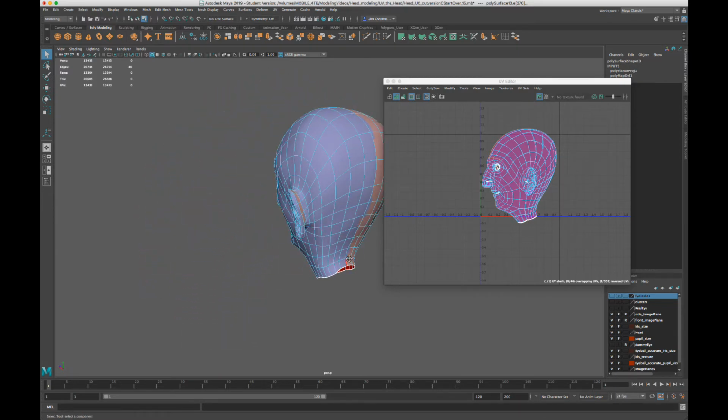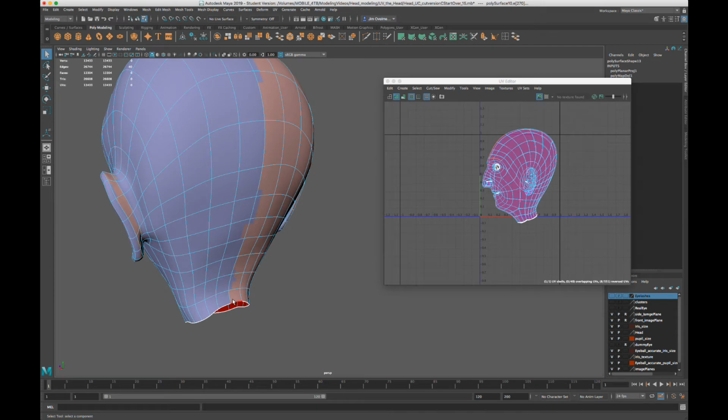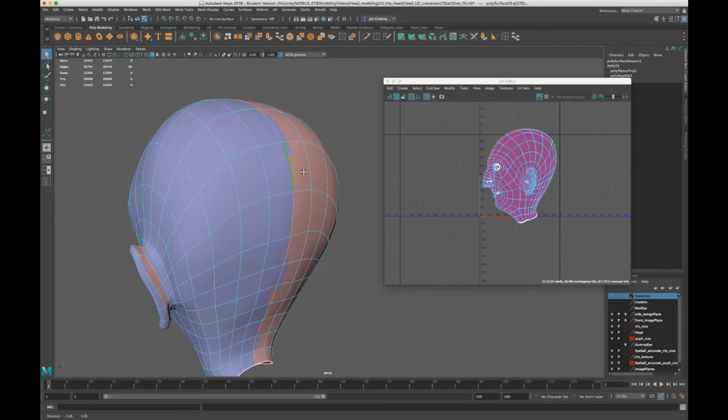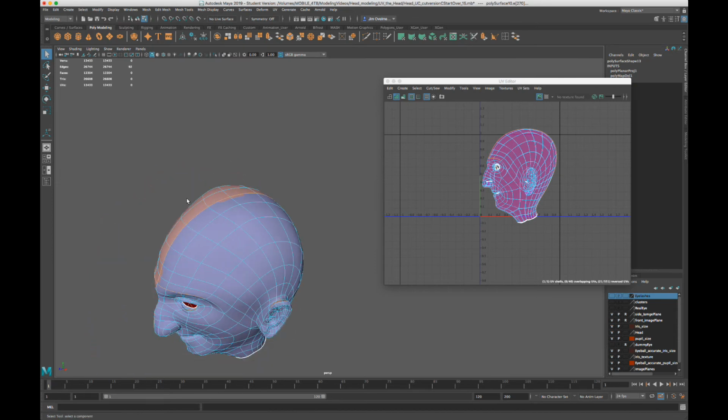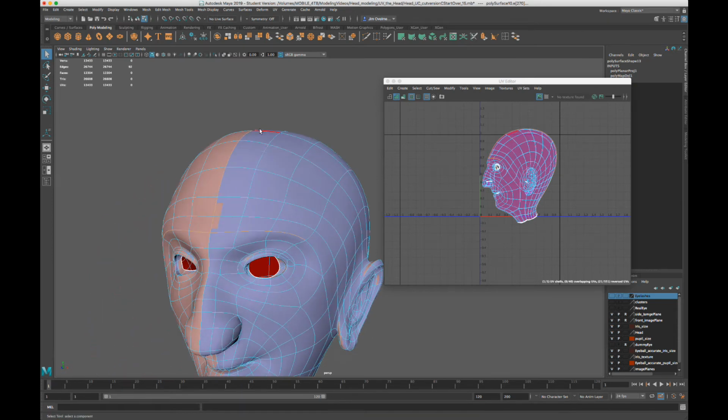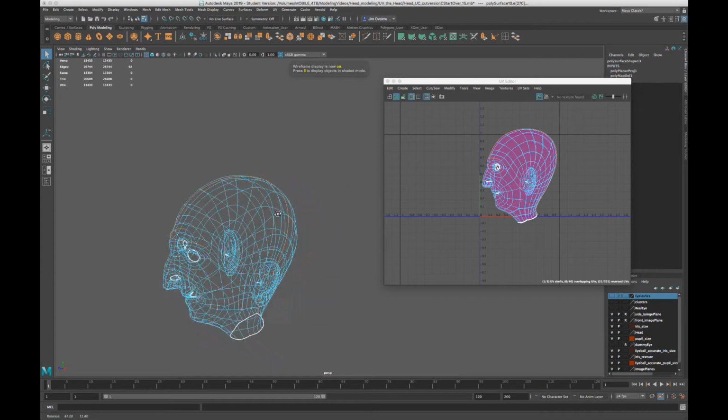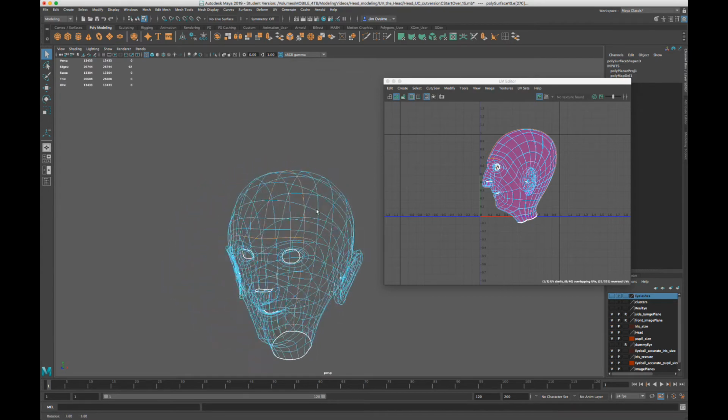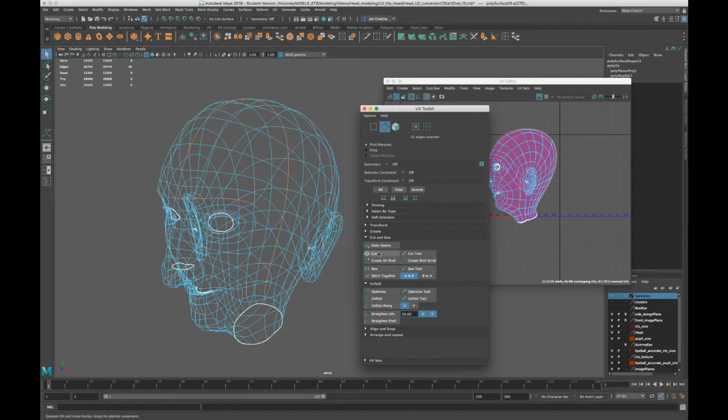If you hold shift down, that is, and double click, you see how that whole line, edge all the way between, becomes selected, that range. So let's double check. Let's look in the view and make sure we don't have any other edges we don't want selected. Here's the toolkit, UV toolkit, and we have our cut tool right there.